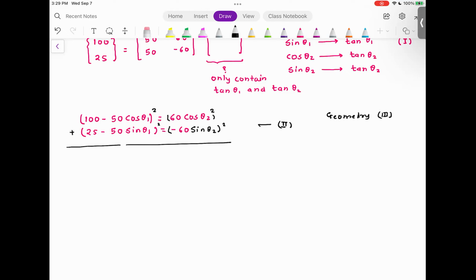Joints 4, 5, and 6 are responsible for roll, pitch, and yaw. And then you will get a very clean solution. Everyone understood this? So if you have any robot that is more than 3 degrees of freedom, the best way to solve this is to cut it into pieces of 3 degrees of freedom each. Only then you will be able to solve.